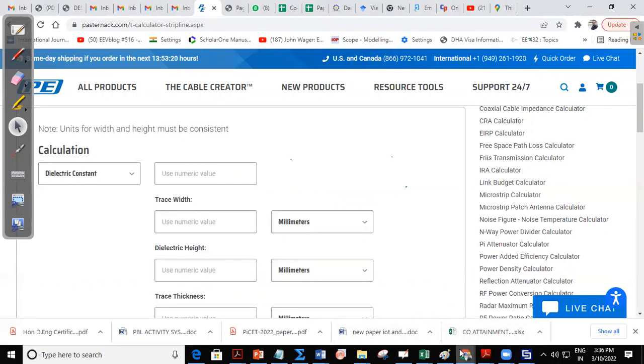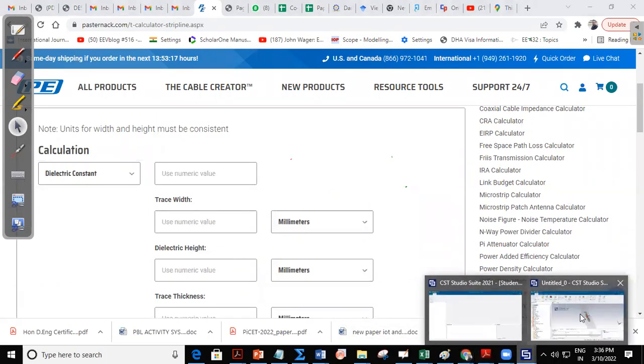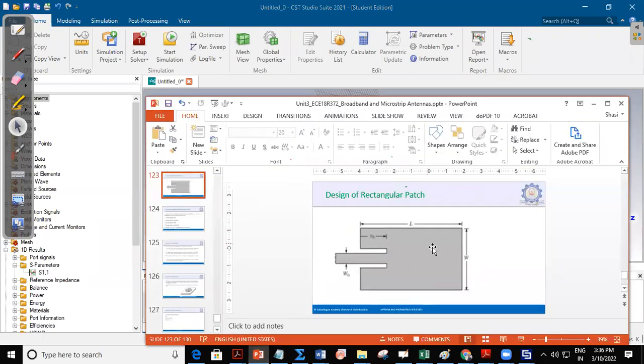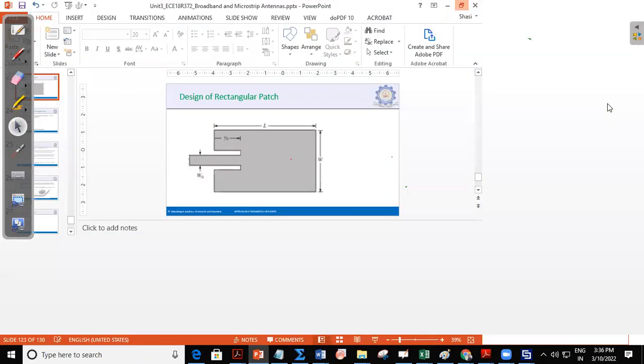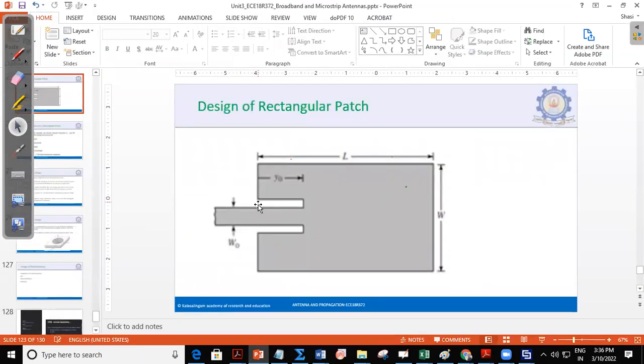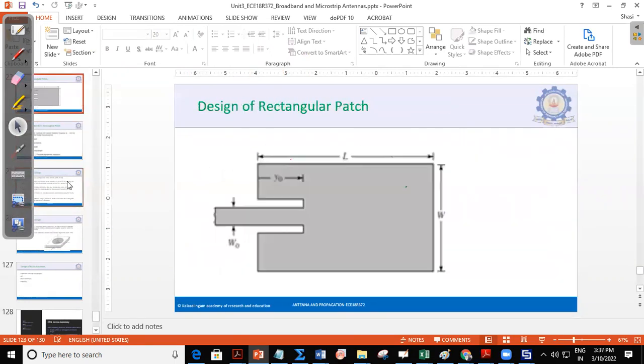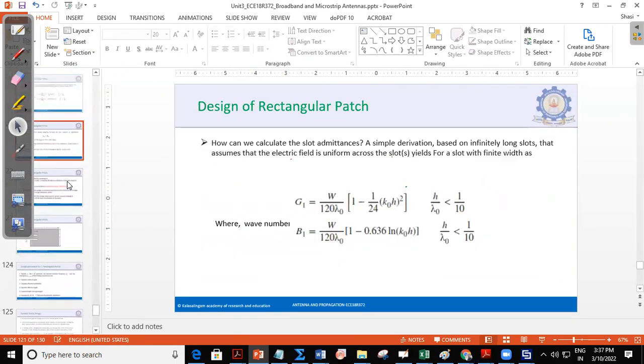So now in this structure we have to create an inset, because if you see here, a strip line, an extra, you can see this strip line up to here we created. We want to create this inset. It means this portion of metal needs to be removed. This length is whatever it is, and we want to remove this. Okay, we need to calculate the patch dimension, and we need to remove this for a length.